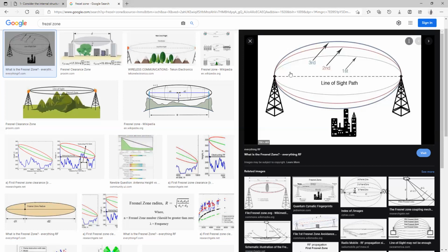If you need to know more about it, like I said, the transmission has many parts of communication. It can go in this direction, this direction, this direction. You know how a signal actually radiates. However, the more effective one will be the line of sight, so the direct path will be much more effective. Within this, there is a certain amount of angle, and that amount of angle of radiation falls into the first Fresnel zone. In the second, there is another set limit, and in the third, there is another set limit of angle of propagation of these signals.